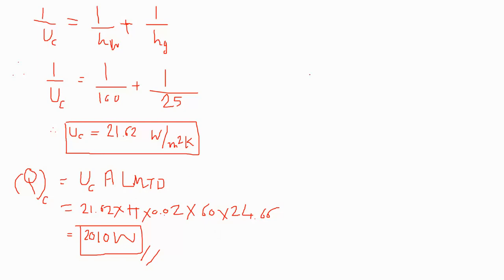Okay. Now, what happens when the pipe is fouled, when any scaling or dust is there? The heat transfer will gradually decrease. Because we have the same area, Q is equal to H into delta T. We have the same temperature difference and the same area, and our heat transfer is decreasing.